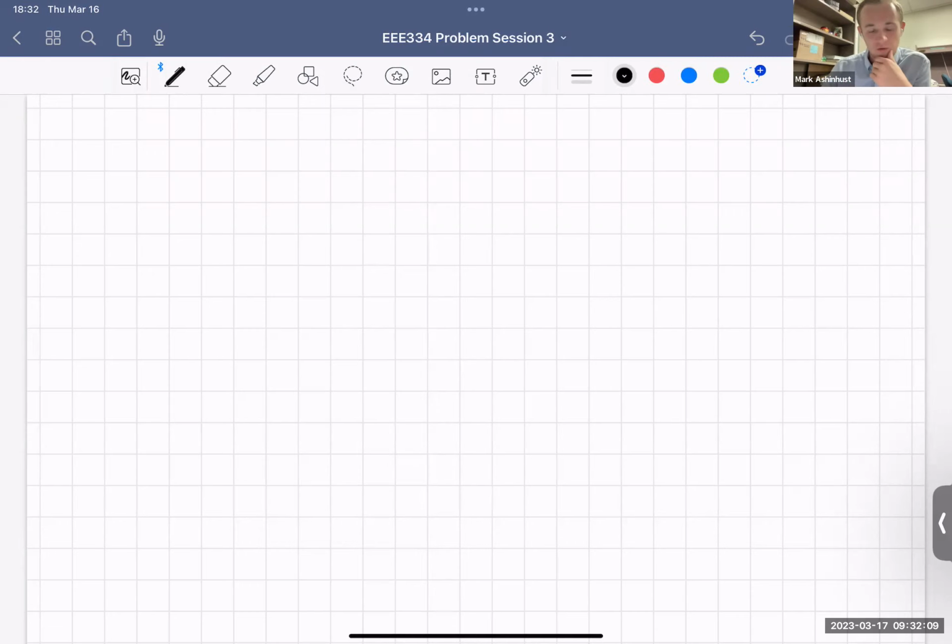This one we're going to solve for, we're missing the resistor. We're going to want to solve for the resistor to ensure that we're in a mode, and that mode is going to be saturation. So what value does that resistor need to be to ensure that we're in saturation? So I'll write out our question here, question number 2.